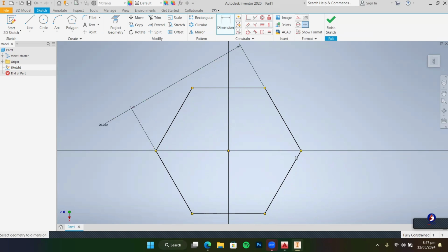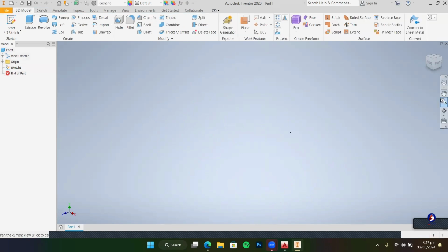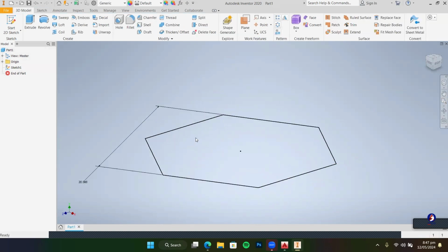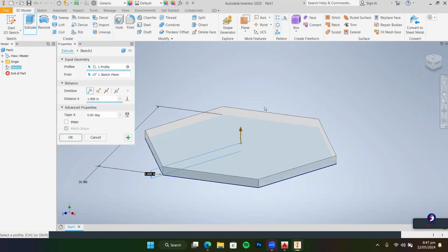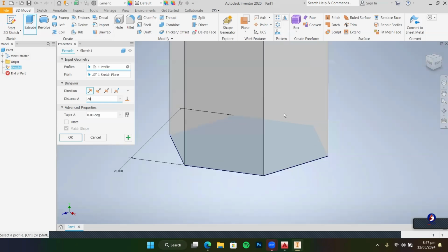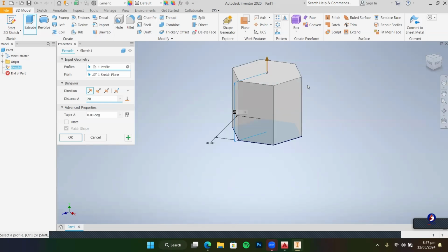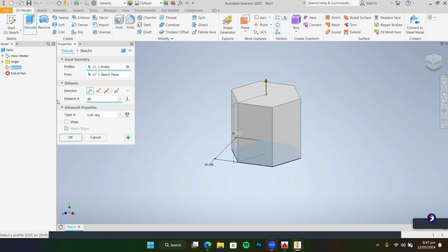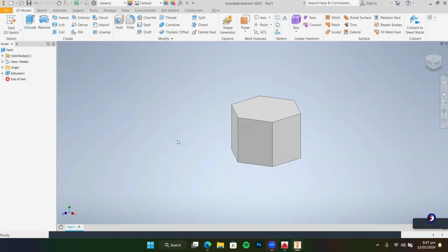With this one, we are not going to draw any circle or use any fillet. We'll just finish our sketch like this. It is missing again, so I'll just click the other side and it will come back. With this one, there's no press pull in Inventor. We have something we call extrude. The height we used was 20, so we use 20 here too. Okay, for it to look real, let us use 15. Now we are done with the 15. You press enter like this, right?